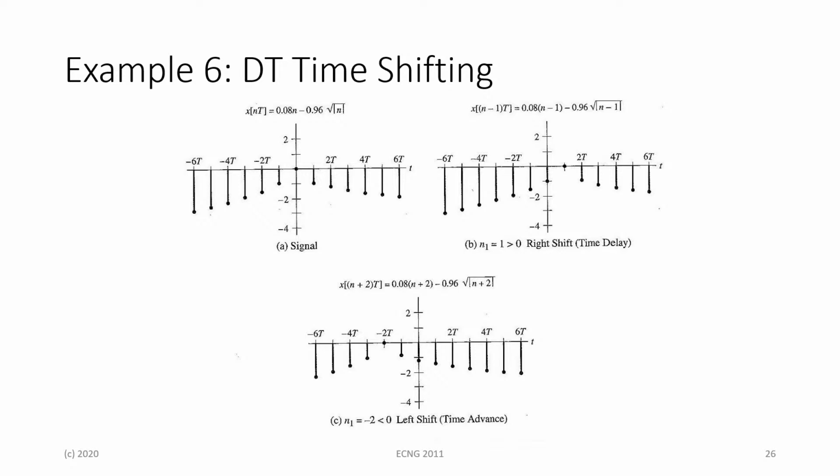For example 6, with the time shifting, it's basically like shifting the vertical origin axis by however much left or right. You basically just shift the signal left or right accordingly by the amount of delay. If it's a negative value, in the case of -1, you shift to the right by 1 unit. If it's a positive value, in the case of +2, you shift to the left by 2 units accordingly and so forth. So yes, it's basically like shifting the vertical origin axis.